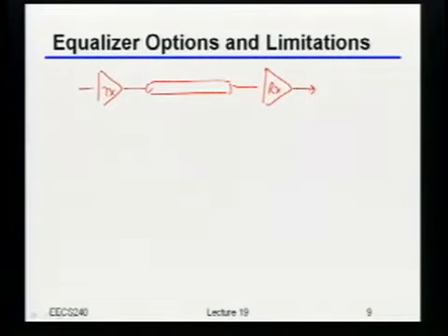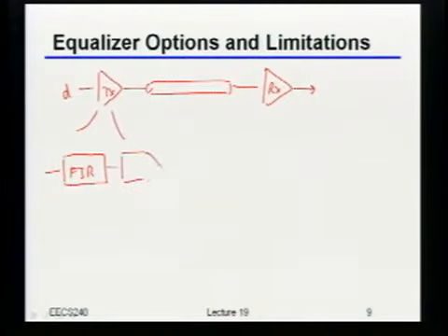In terms of how you'd actually build something like this in the transmitter, the way most people think about it is, my inputs here are digital bits. So I can basically take those digital bits, pass them through some digital filter, which is usually an FIR filter, meaning finite impulse response filter, and then feed it into a D to A converter. Okay?